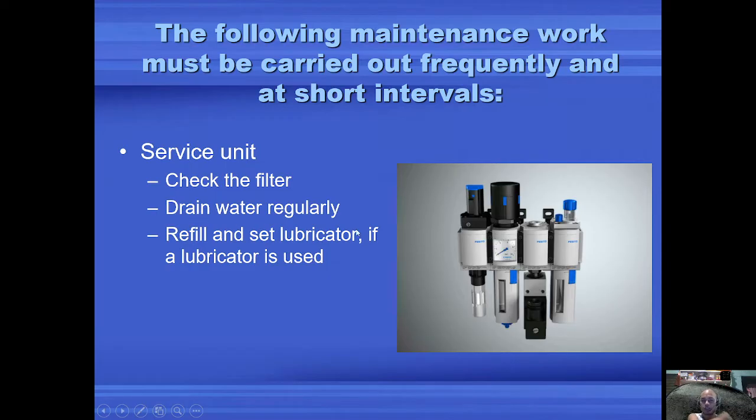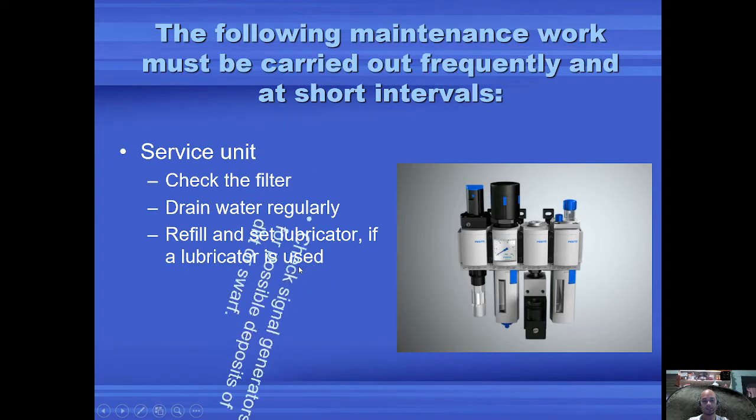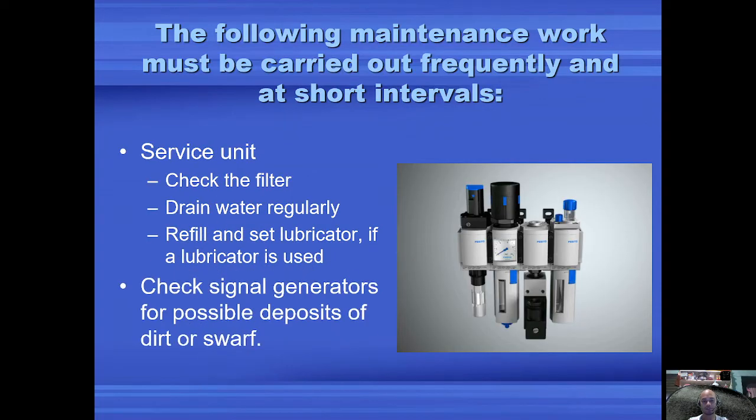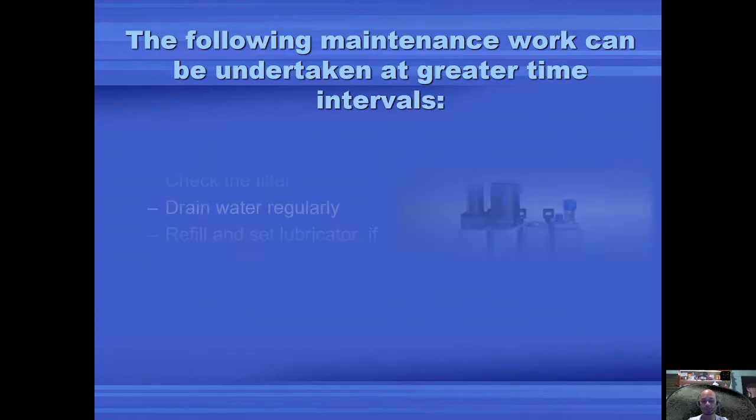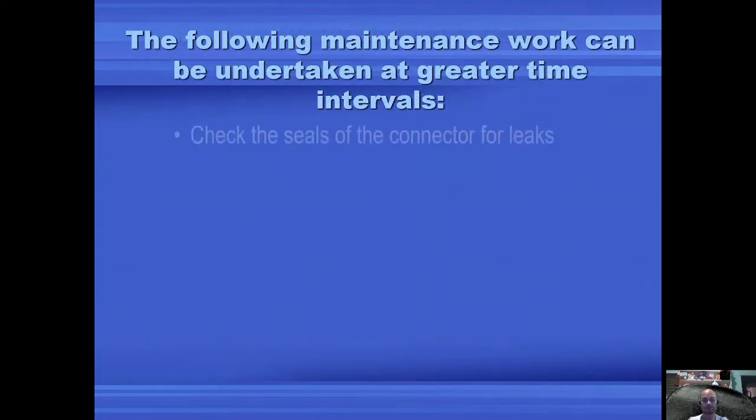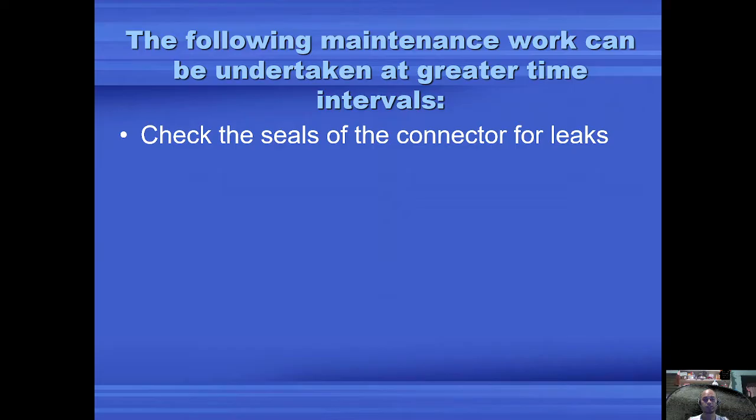Refill and set the lubricator: always check the oil and refill if it needs more, if a lubricator is used. Then check signal generators for possible dirt.